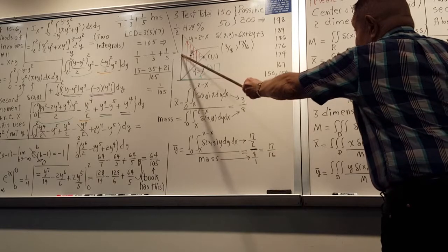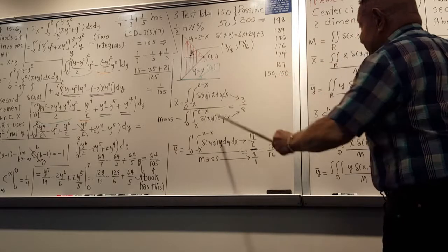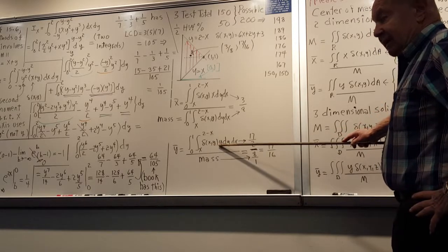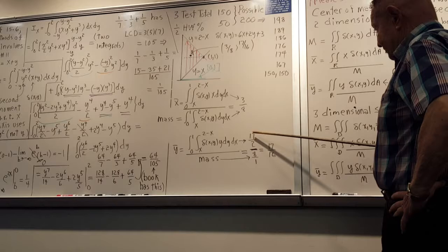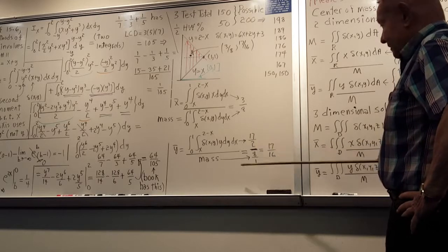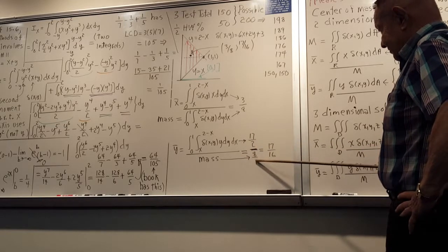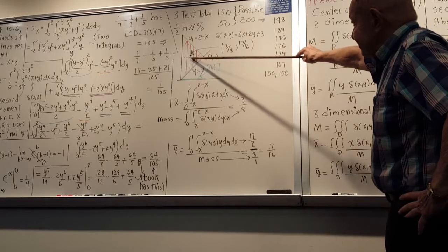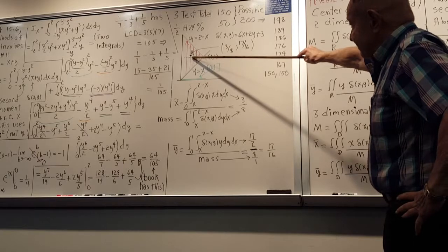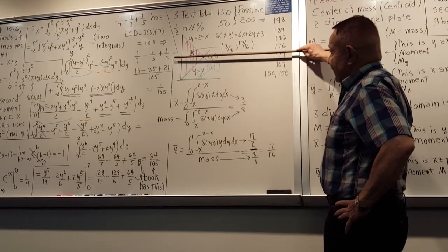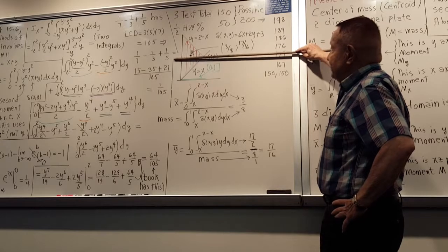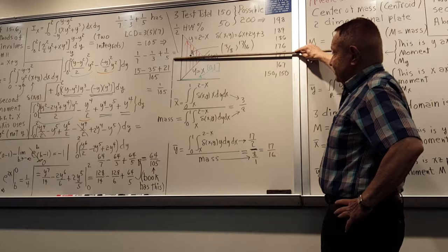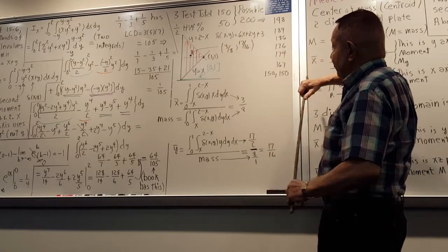So you are 3/8 in, and then for your y bar, you have your density times y, and that'll give you 17 halves, and your same mass is 8, or 8 over 1, so you have 17 over 16. So you're just above the line of symmetry of the area. Your line of symmetry of the area, of course, is here at where my stick is, going through 1, 1.